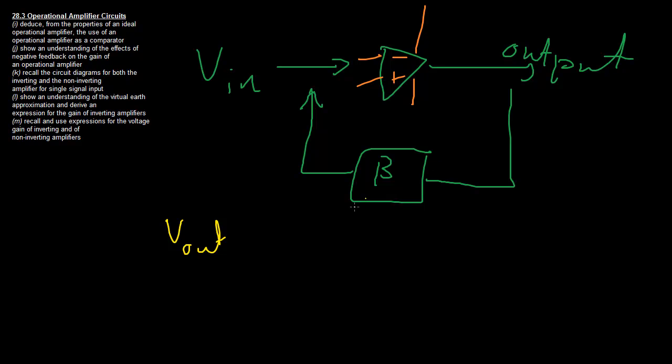You don't really need to know the full mathematics, but what we figure out is the voltage out is equal to the gain, obviously, times the voltage in, plus the fraction of the feedback, which is the output we're putting back, times voltage out. This is a bit of a weird equation because voltage out appears twice, but we can solve it algebraically.